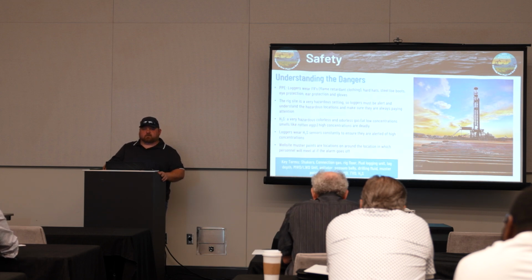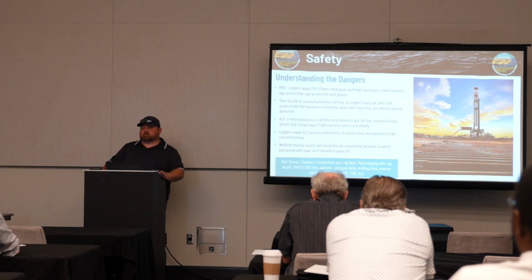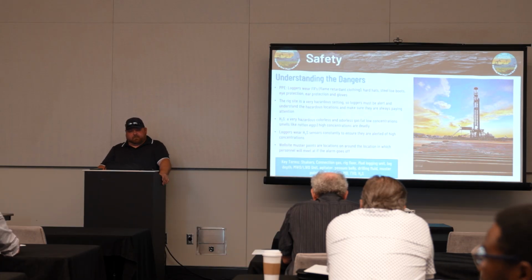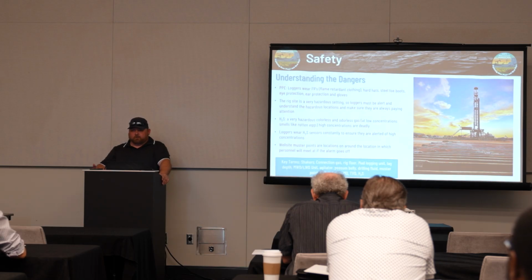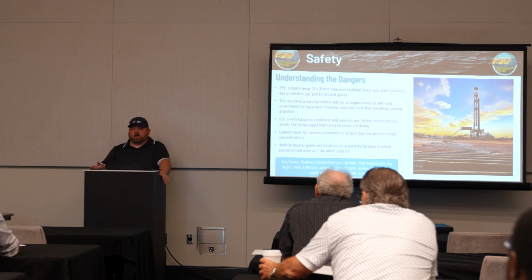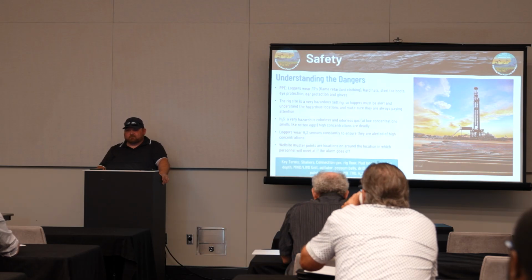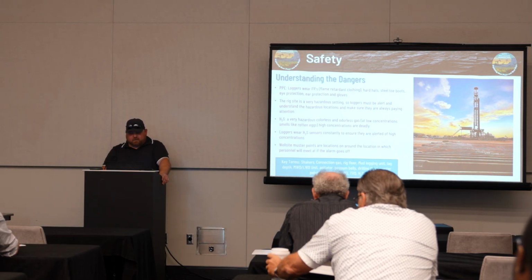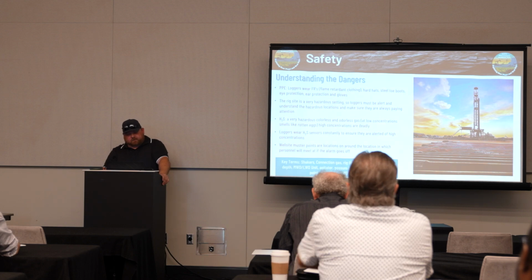On drilling rig locations, know the muster points, the hazards, and even how to get away from the hazard. When you hear an H2S alarm, your immediate instinct is to run. Well, if you run off the side of a rig location or off the side of a rig, it's going to hurt. So making sure you know where you're going in those times is very important.